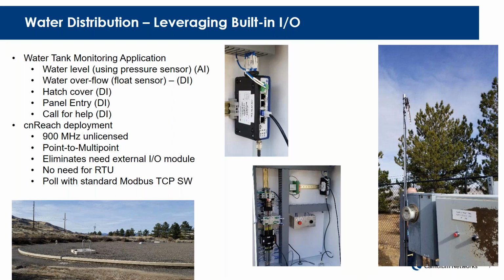And in the upper right, you'll see a Yagi antenna coming out of that cabinet. And that's pointing back to their central SCADA master control center, which is about 7 miles, 11 kilometers away down that hill in the center of the city. So imagine water tanks, lift stations, locations all around the city that are using this type of automation to manage the network.